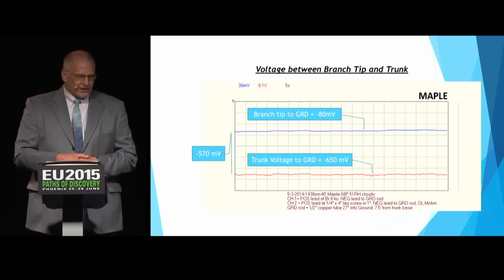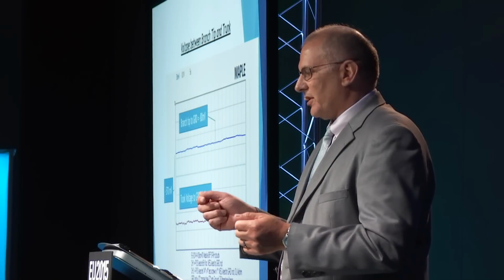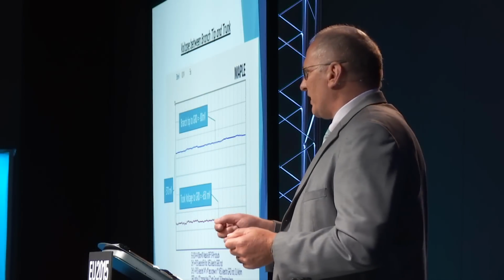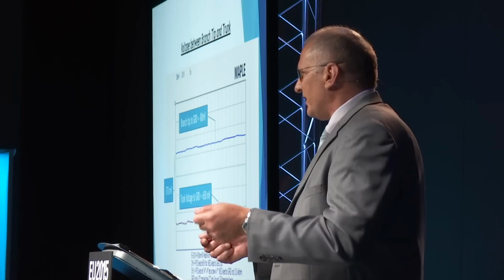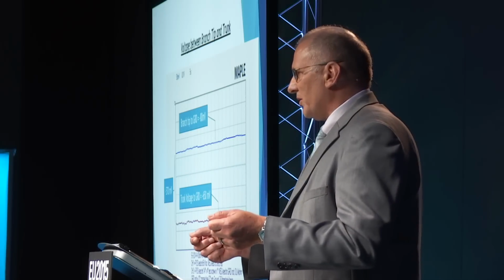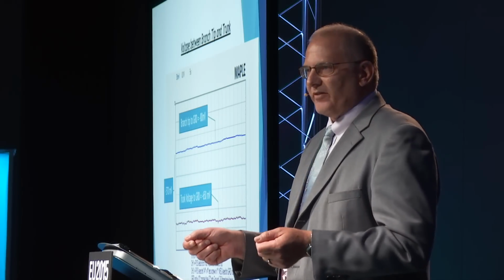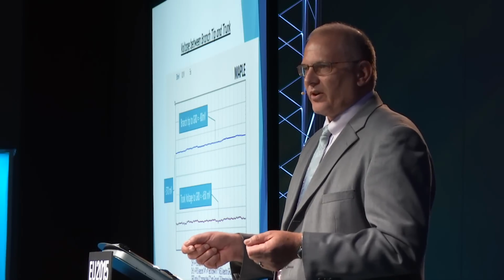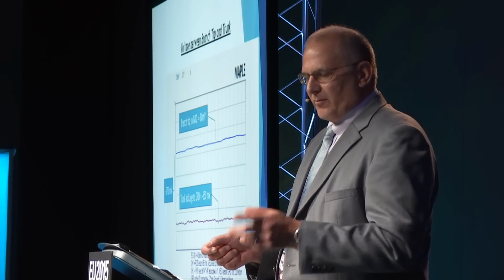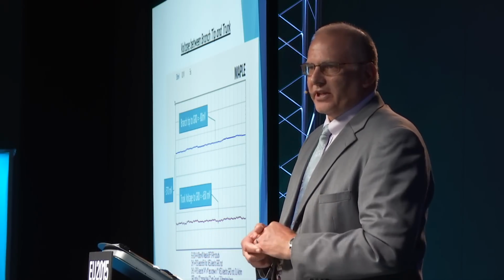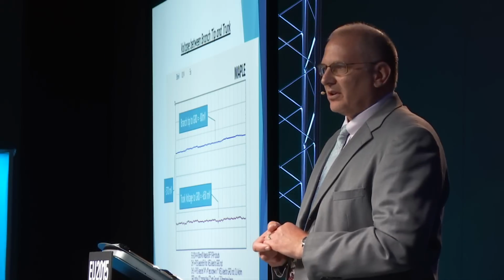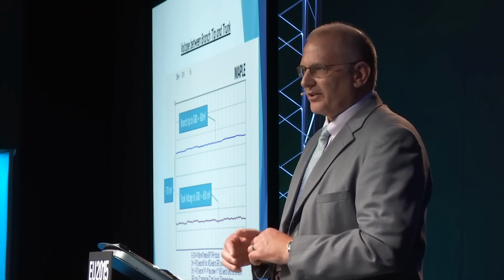Now, I assume that the negative voltage is the same as you would see if you took a battery and a voltmeter and you took the positive lead of the voltmeter and you measured the negative lead of the battery, and vice versa, you'd get a negative voltage reading. And since the positive lead is at the negative end of the battery where the excess of electrons is, I'm saying that these negative voltage readings here are also showing excess electrons.